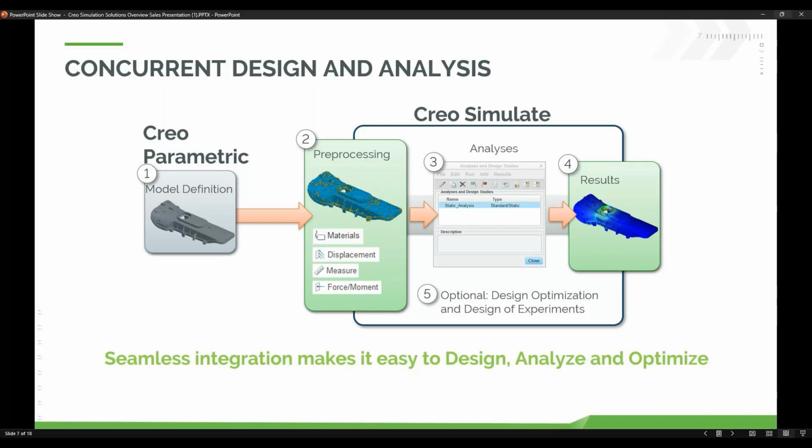I like to refer to something called the simulation pentagon. Everybody's familiar with the Pentagon, five-sided building, but you need 5 things in order to do a simulation. And I don't care if it's Creo Simulate, if it's ANSYS, if it's a SolidWorks product, if it's an NX product, you need a model. We have a model with Creo here. You need to specify a material so that you know how this model is going to behave. Obviously, steel is going to behave differently than aluminum or wood. You need to know how this model is constrained, how's it being held, how's it being used.